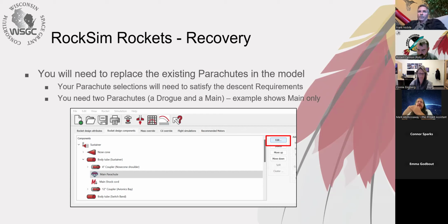Usually they're not sufficient for the flight because as part of your challenge, you're modifying the rocket itself. Say the parachute that they give you from the vendor is sized for a 10-pound rocket, which is fine and all until you go and add 2 more pounds of electronics challenge components. Now that parachute that you got with the rocket is no longer sufficient to meet the safety requirements. So as you evolve at each milestone and as things change, you're going to go in and change those parachutes.